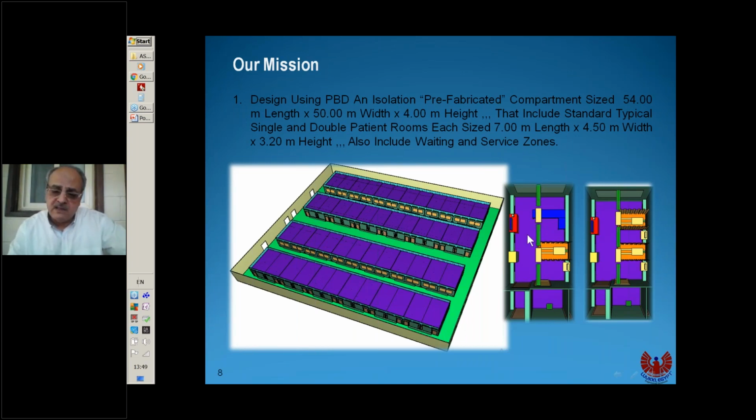And the supply air will be here. So we have exhaust or return here, and exhaust or return here, and here the supply air. At this airlock, we have a separate air washer from here, and return near the floor also.